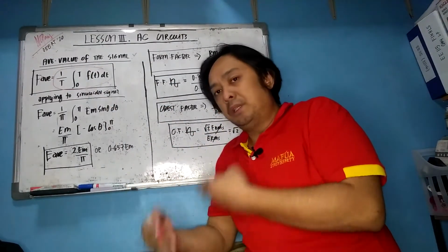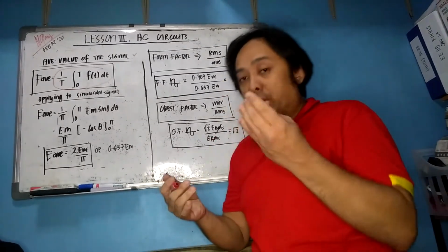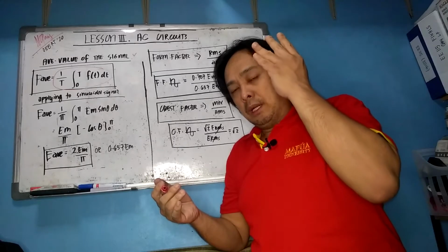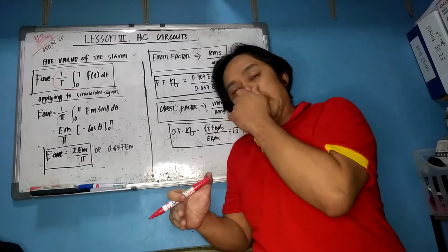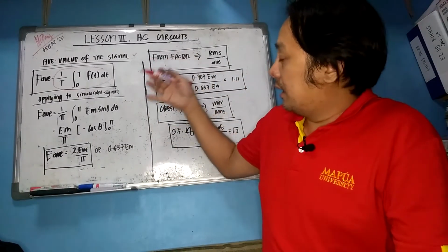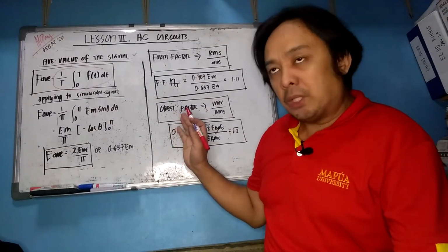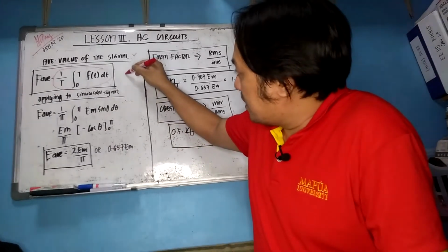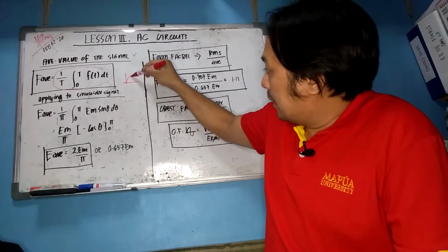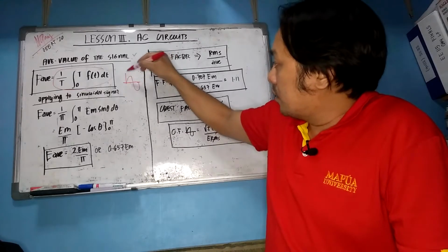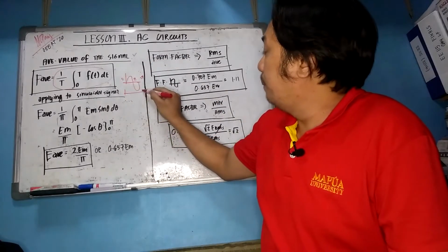So, this is the same thing, that the signal average, or F average, is simply 1 all over T, the period, integral from 0 to T, F(t) dt. Now, you need to apply the sinusoidal signal in getting the average. We'll do the same pattern as a while ago, but the only difference is the period T. I'll draw again a sinusoidal signal from 0, pi, and 2 pi, and you have the whole period T.